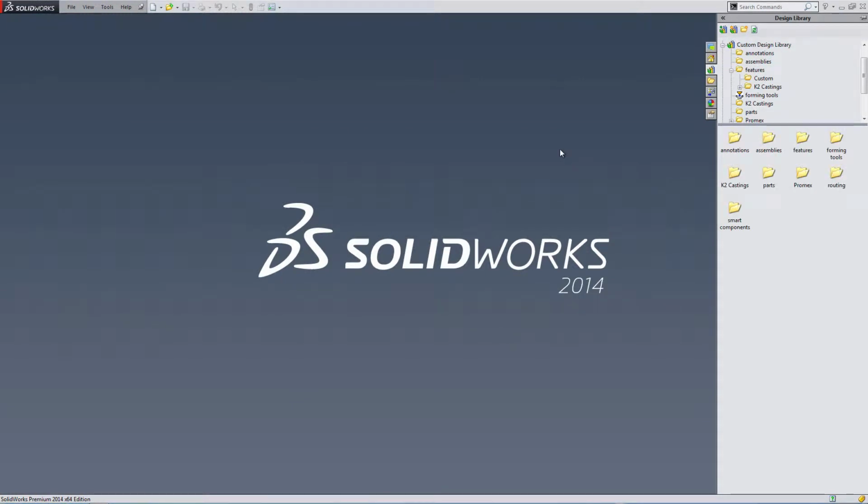Okay, so under the custom design library, what you'll notice is there's a folder called Forming Tools. In this case, I've already turned it into a Forming Tools folder, but originally it looked just like the rest of them. What you do is you right click on the folder and click this button that says Forming Tools Folder, and it will then recognize that as containing forming tools inside of it. So you'll have to do that as part of creating a new Forming Tools folder with forming tools in it.